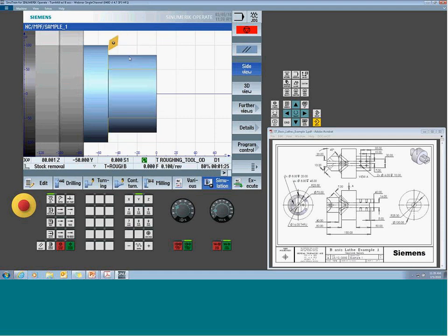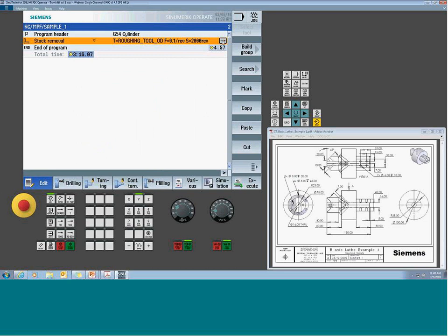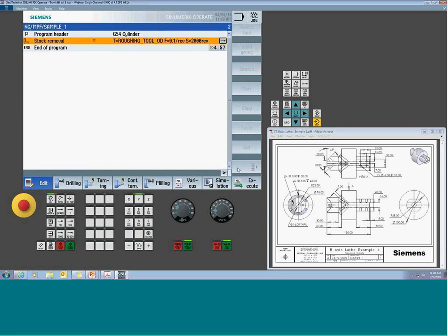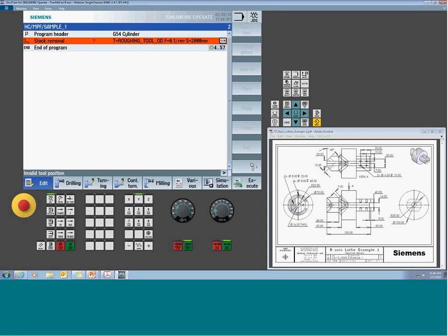Take a look at the orientation, right? So this is a 55-degree insert with minimal lead angle, probably 5 or 7 degrees. So you see that insert was almost vertical against this back wall. So as you start to drive or control the B-axis, maybe I plug in a value of 45 and simulate it, it's going to tell you whether or not it can get to that location.